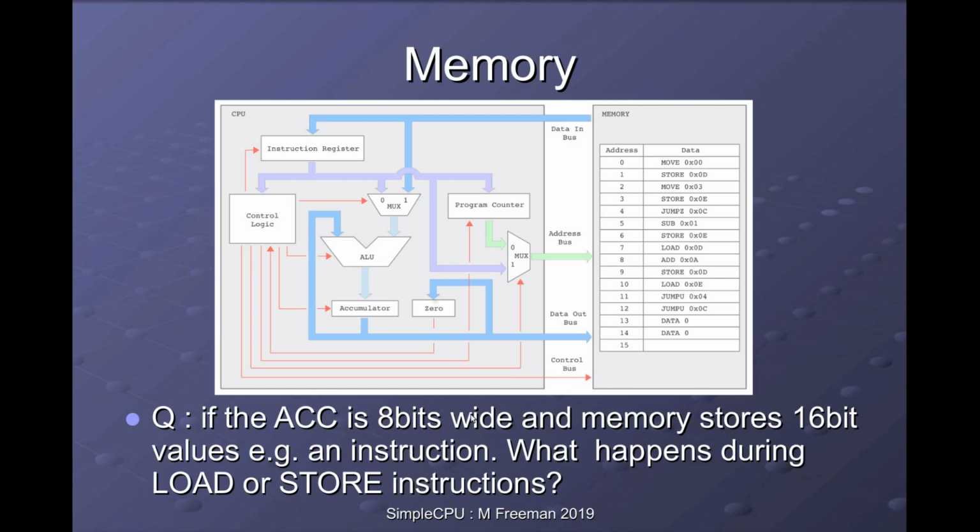There are some couplings between the two, but the size of the instruction and the size of the data are generally independent of each other. So this raises some questions about how we configure our external memory. What happens when you read or write data to a memory location, because each memory location at the moment is 16 bits in size, because obviously we'll be reading and writing an 8-bit value from a 16-bit storage location.